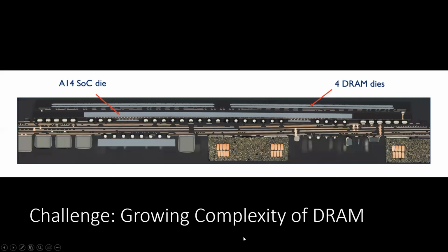For example, let's say if we want to probe a bus and sort of understand what's the frequency of refresh commands that is being sent, or use this type of probe and fault inject type of methodology, that's really not possible with stacked DRAM. So on Apple's A14 SoC, the DRAM die is inside your package. So there are no pins accessible where you can probe and understand more about the system.